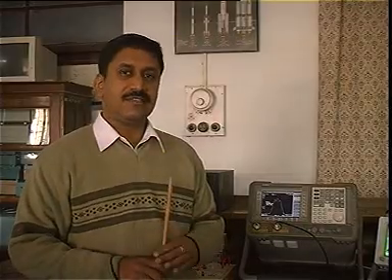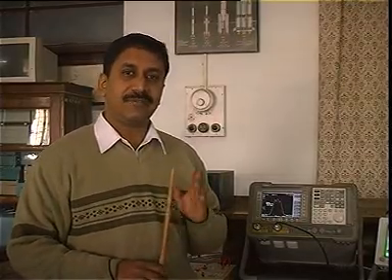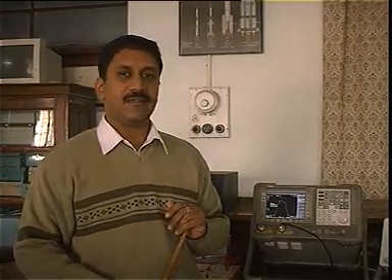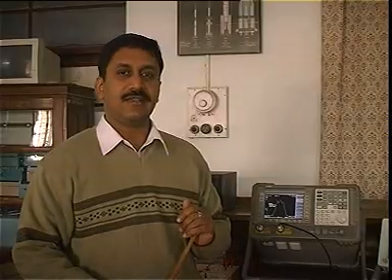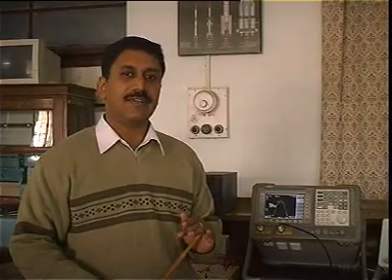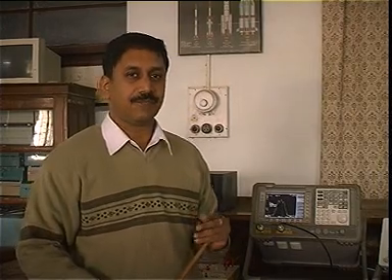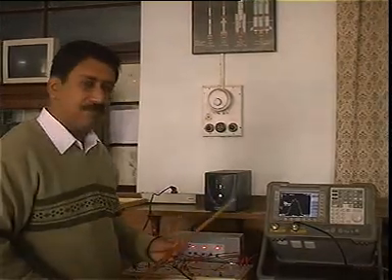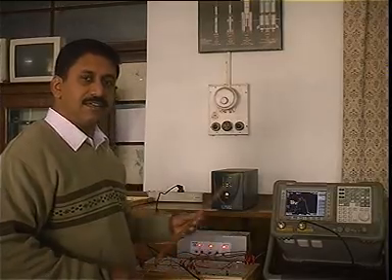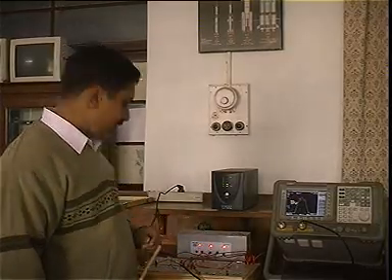We can also generate amplitude modulation by suppressing the carrier. Okay? So we transmit both the sidebands, but with the carrier suppressed. The carrier power is much less here, and so we call this scheme double sideband suppressed carrier. So how do I make a suppressed carrier here? I need to bring down the carrier power. There is a facility in this kit by which I can reduce the carrier power.